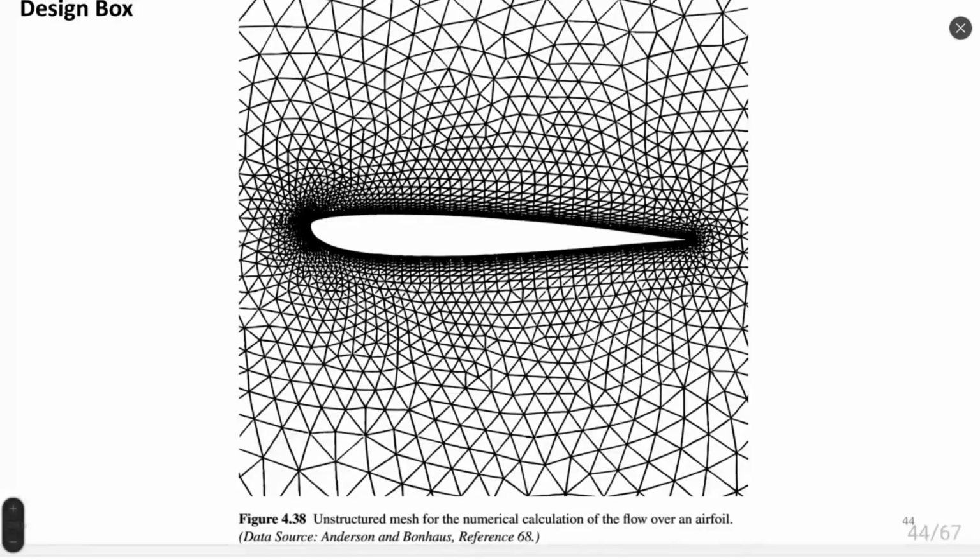For example, if you try to evaluate pressure distribution, your losses would be very small. So your simulation would be accurate for such a mesh. But if you will try to simulate boundary layer and velocity distribution on boundary layer, probably you will lose all information.